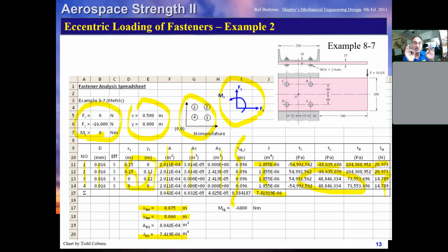If I ask you for the bending stress to evaluate bending of the fasteners, you're going to look at what our two plate thicknesses are. Your eccentricity is 1/2 of the sum of the T's, right? T over 2 plus T over 2. That's your eccentricity.